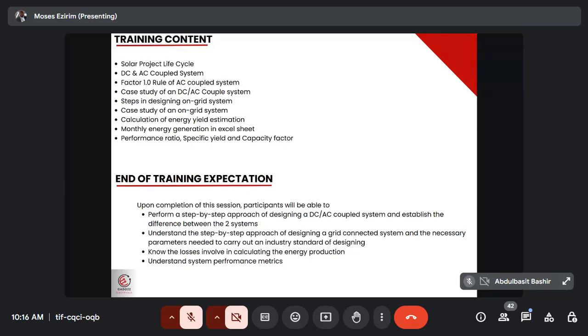So once you are able to log, you'll be able to identify the load pattern, that these clients consume much load in the evening. All right, so what you need to do, once you do your load project, you can advise the client to move his operation to the day.